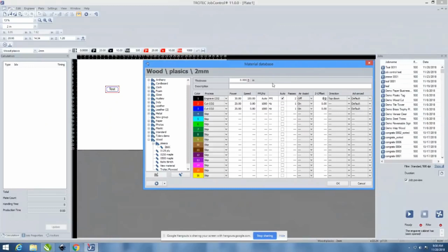Perfect. Thanks, John. And also, Anthony, I should mention the Z offset. We have multiple videos, like the out of focus method that I think Mike Clark did. If you want a blacker engraving on the Trotec plastics, you might want to put it a little bit out of focus. Again, I mentioned with the acrylic, if you're in focus on the acrylic, it'll engrave white.